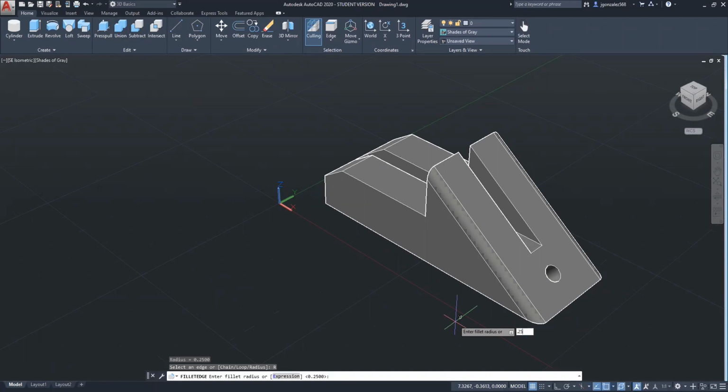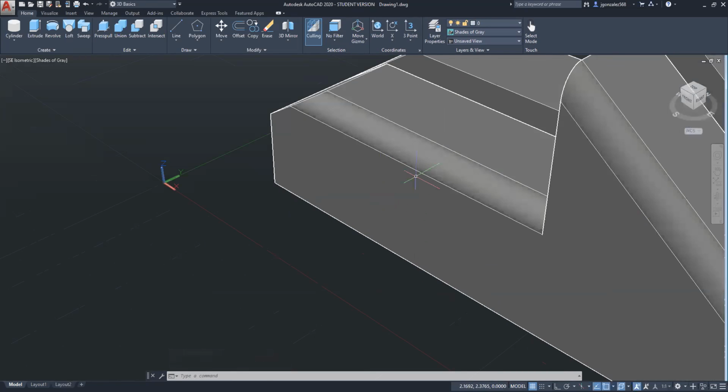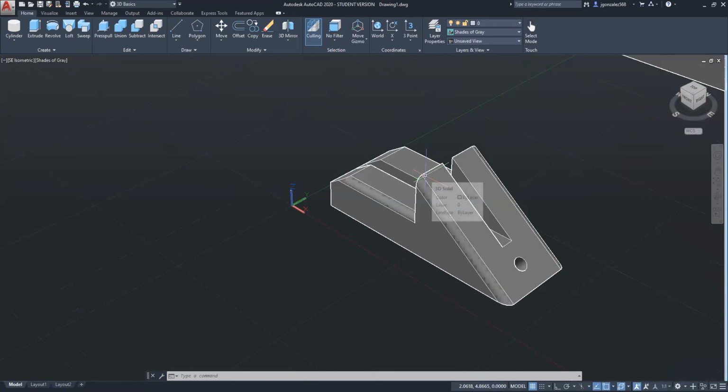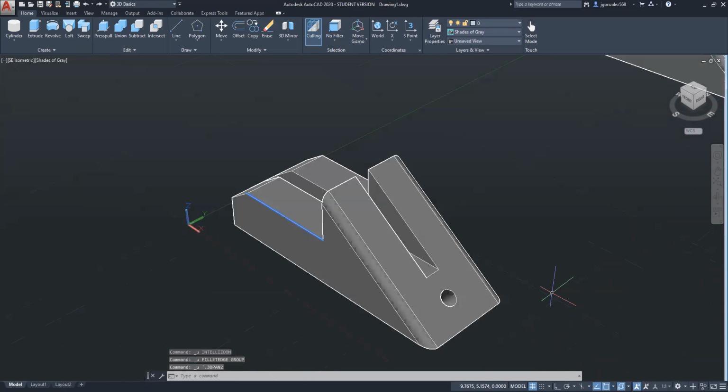Okay. And then at this point, you select an edge. So I already selected an edge, so I can do a different edge, I guess. And then once you select it, press enter 2 times. You should create a little dip. Got it. That's where I wasn't pressing enter 2 times, so I didn't really know what I was doing. Oh, okay. That's all good then.